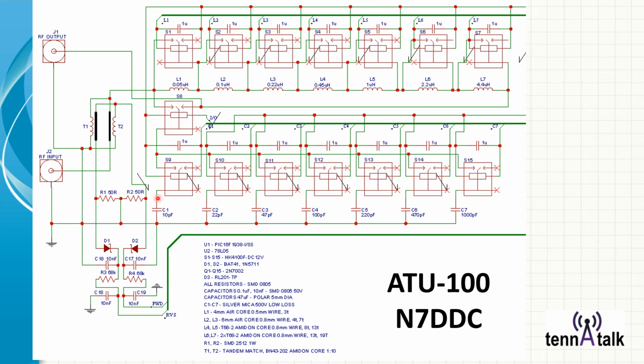And that sample then gets divided down, and then you have these 2 diodes back to back to actually measure the forward and reverse currents. And those forward and reverse currents are then converted into signals, and this little green bus bar goes back to the microprocessor, giving it 2 analog inputs of the voltages, the forward voltage and the reverse voltage.